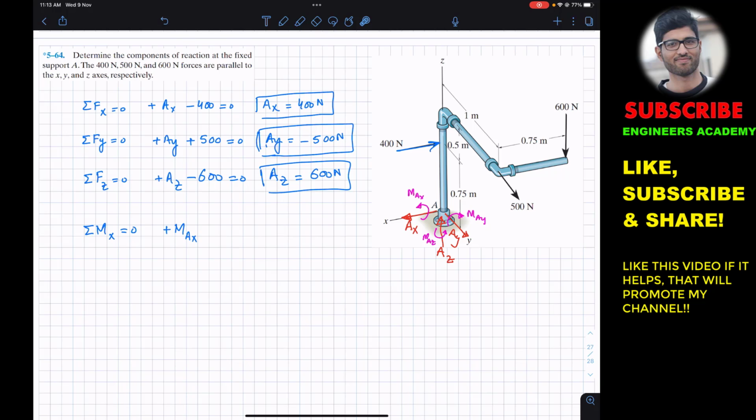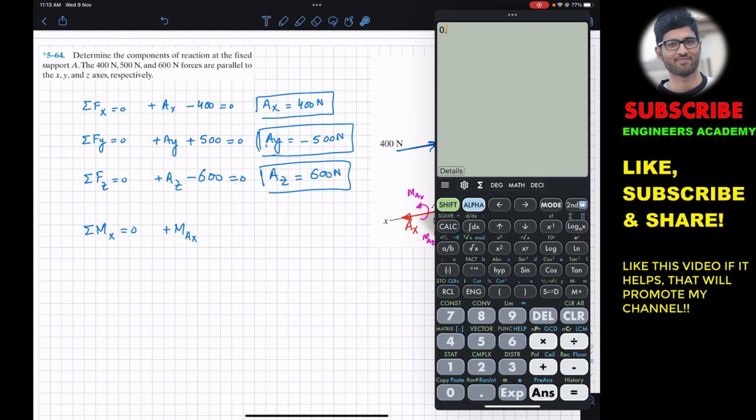The moment produced by this 500 Newton force about the x-axis is 500 multiplied by the perpendicular distance between the 500 Newton force and that x-axis. If we extend the line of action of this force, the perpendicular distance of this force from the x-axis is 0.75 plus 0.5, which is 1.25.